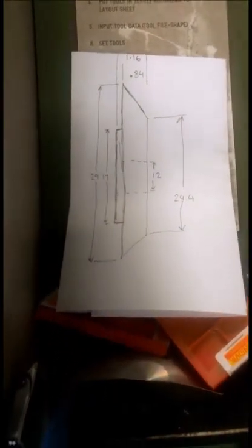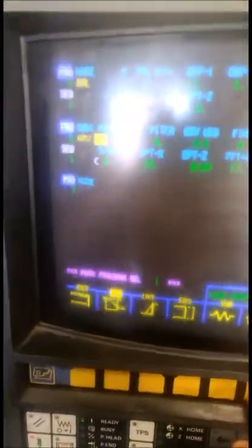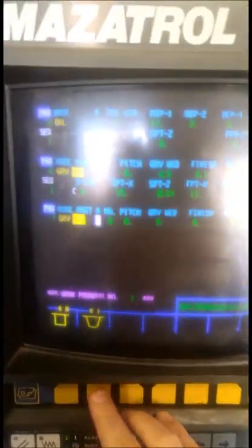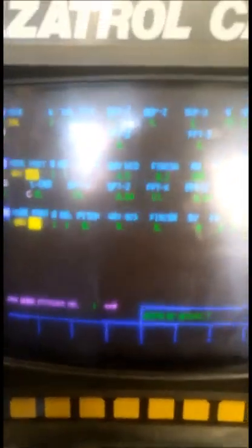Starting point will be 0. Finish point. So we've got to get through at least 1.6 for that, plus then I've got to add in the tip. So I'll just say 6, just for good measure. And then all that's left is to part it off. So we'll run another groove, out, trapezoid, 1 groove, no pitch, 3 mil wide, because we're just doing the width of the tool this time.